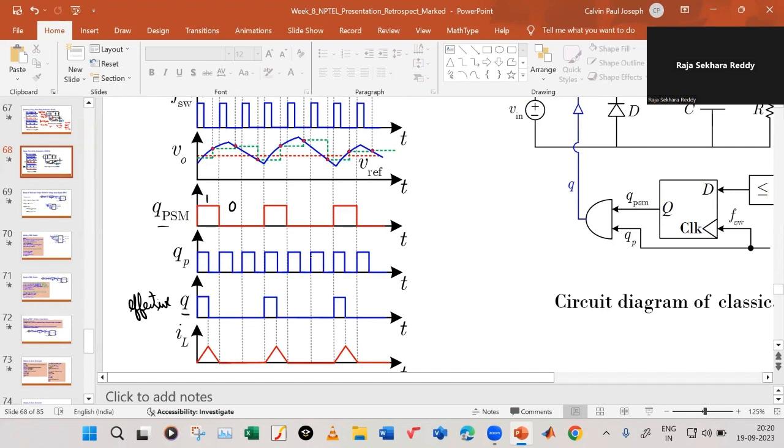Now you're saying over here it has become more, so this should become 0. But it has not changed till it comes here. Why is that? Because at this instant only this clock is getting the switching clock. So when this gets the clock, only then will this get updated. Till then it will hold on to the value 1. Once it gets the clock, it will fall to 0 and maintain that value.